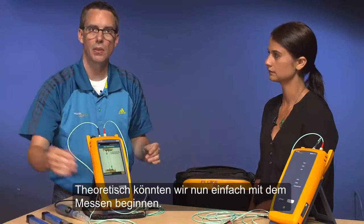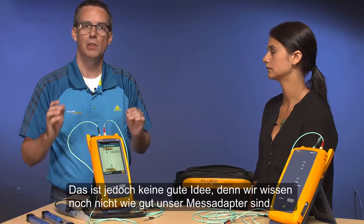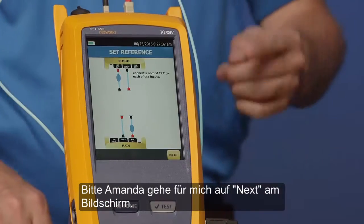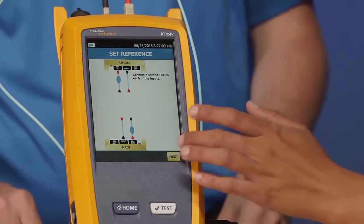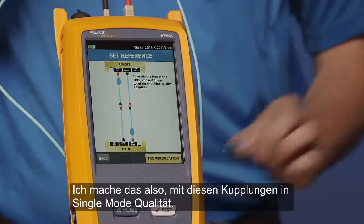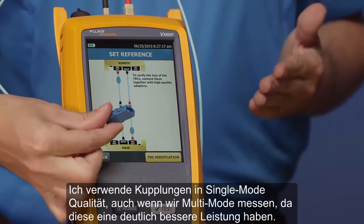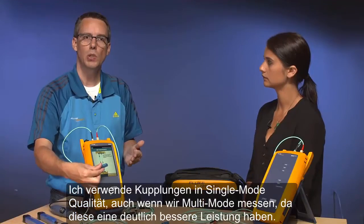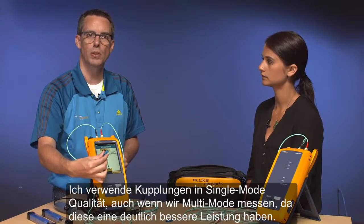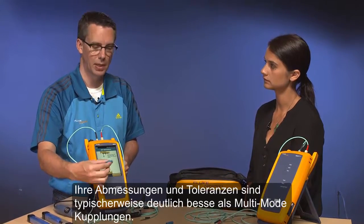So we could, in theory, just go off and start testing, but that would be a bad idea because we don't know how good our test reference cords are. So Amanda, go ahead and tap next on the screen for me. It's asking us to join the two cords together, so I'm going to do that with these single mode rated couplers. Now I like to use single mode rated couplers even though we're doing multi-mode testing because these have much better performance. Their dimensions and their tolerances are much better than multi-mode couplers typically.